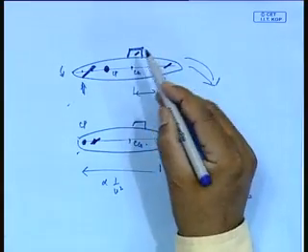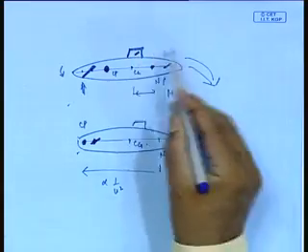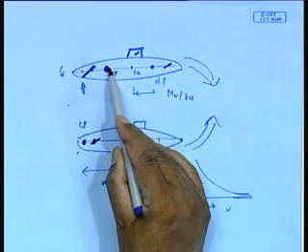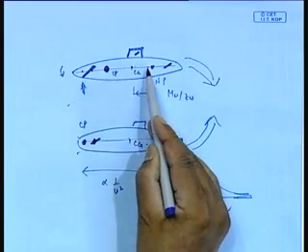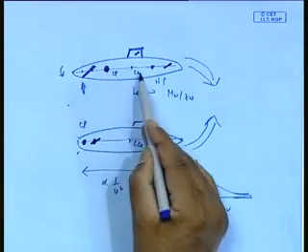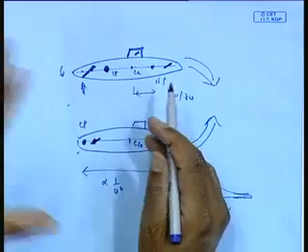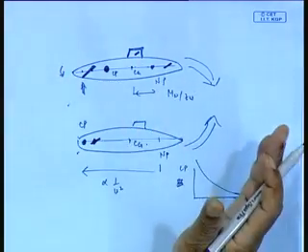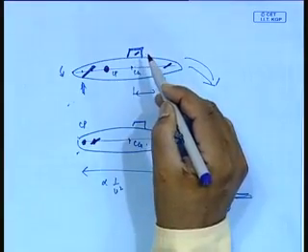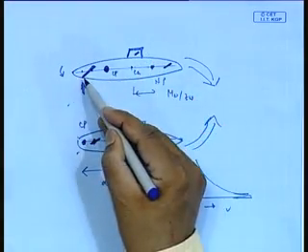So the difference is that this is slightly back, but the question is that Cp is normally aft of this. For it to actually go forward of that, it would have to go at such a speed which is impractical. So normally Cp never goes forward of the bow plane. So as far as the bow plane is concerned, there is never reversal, that is an important point. So for the bow plane we do not worry, but for the stern plane there is a big worry.